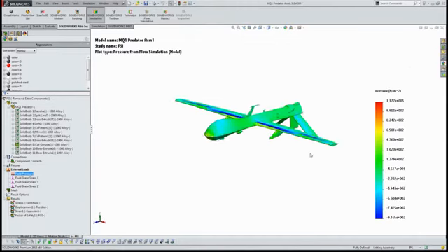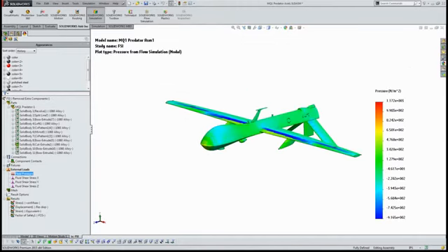So here are my fluid pressures, and the meshes are completely different, right? The mesh from the flow solver is completely different than the mesh from the FEA solver. The types of meshes that are adequate in both cases are very, very different. So it does a 3D interpolation to get the correct pressures on here.